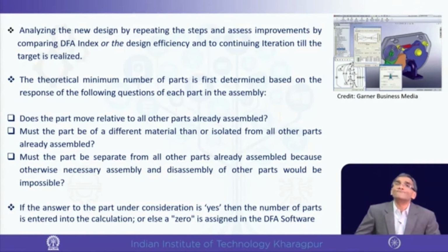What is this? Now, if a part is not separate, if it can be combined into one, then that is the advantage, so that we can bring the number of parts to a minimum. If there are 2-3 parts being machined, fabricated and added, instead we can mold it through a casting process, and in one part multiple configurations can be brought in. So it will become one part.